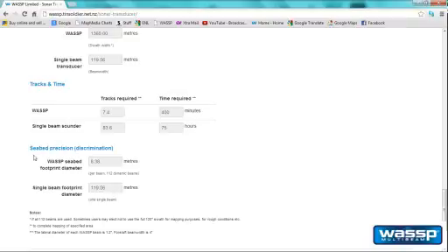Here's the big but again, the seabed precision. So the WASSP, each footprint on the seabed is 8.38 meters, which is pretty respectable in a 400 meter depth, versus the single beam footprint of 120 meters, which doesn't sound too bad, but when you consider that's bigger than a football field, then it really does bring into question how reliable that information is.